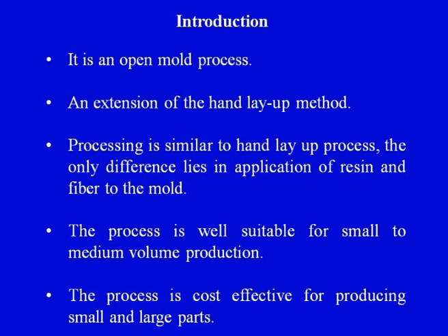Now, coming on to the spray layup process, which is fairly similar to the hand layup process, but there are few distinct differences between the hand layup process and the spray layup process. Here again we have to combine the fiber and the matrix, or the fiber and the polymer, together in order to make a composite product. The spray layup process, as we have already seen, is again an open mold process. It is a further extension of the hand layup method.